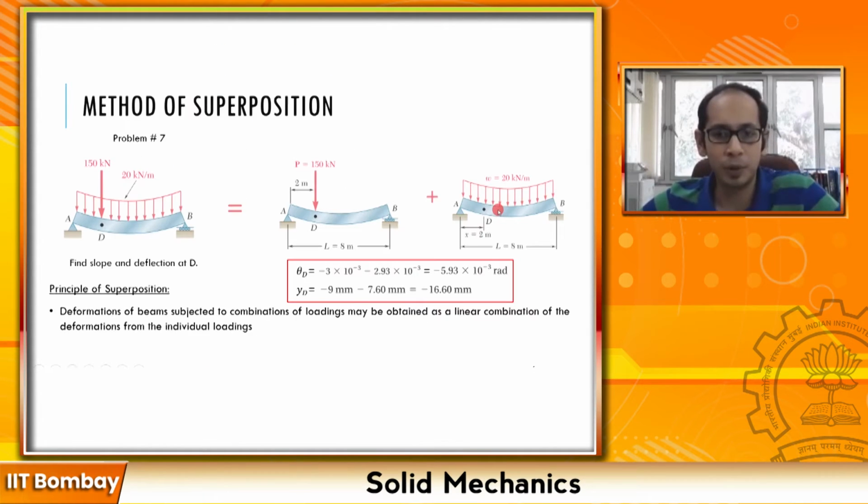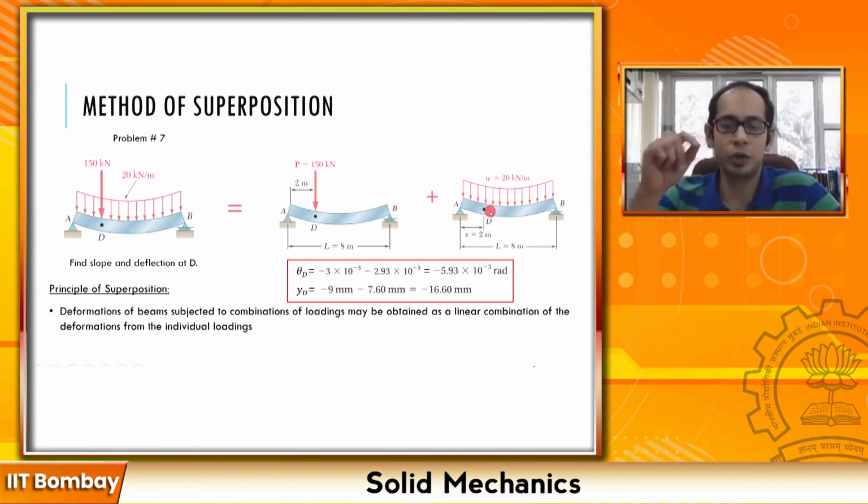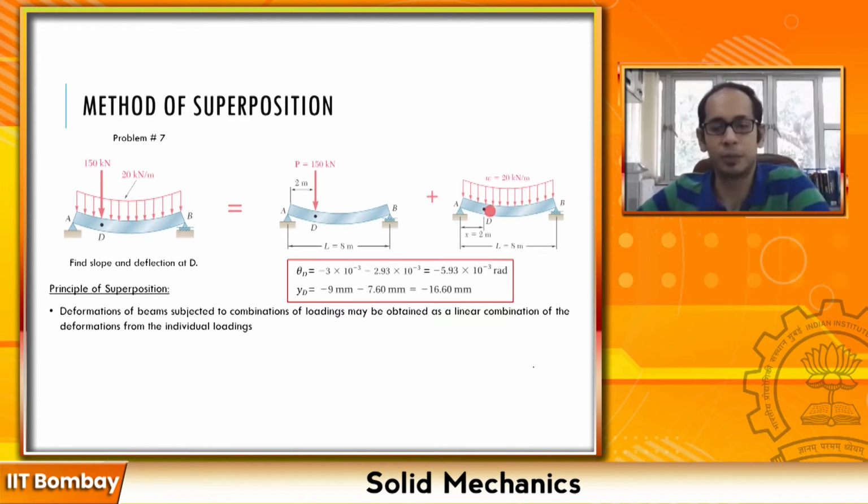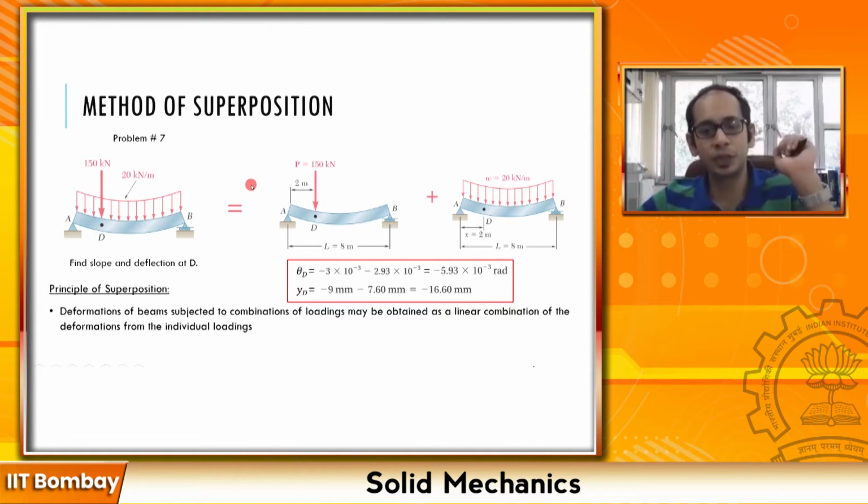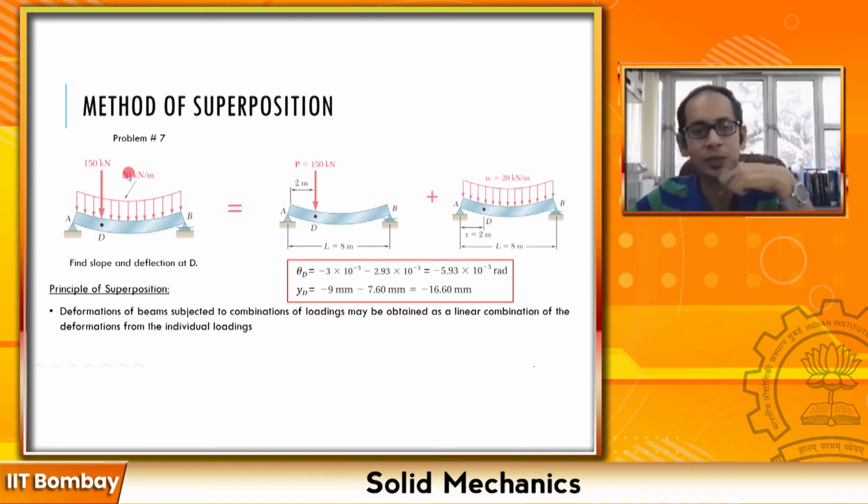Now the particular problem example is not solved here. We are not going to solve that. We are going to solve another example, but you might want to take a look at any one of the textbooks, go to the back pages, pick out the expressions for these standard cases, and see whether you get the same deflection at D, y_D, which I previously wrote as delta D, and the same theta or not. Okay. So this was the principle of superposition, as it is applied to statically determinate structures.